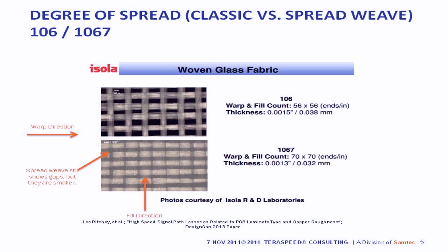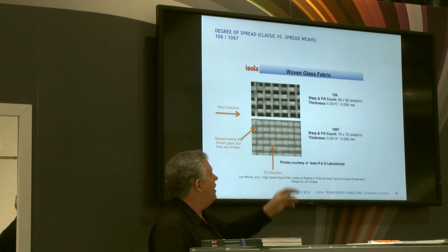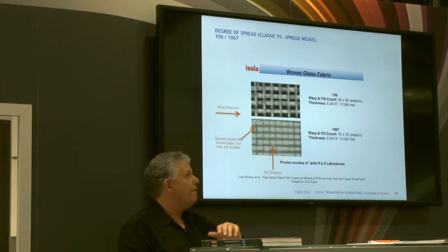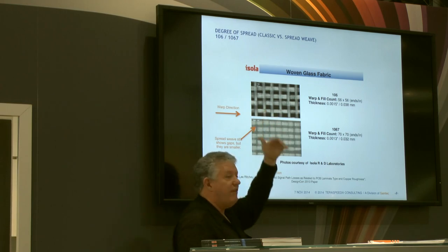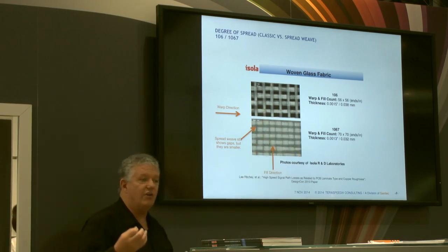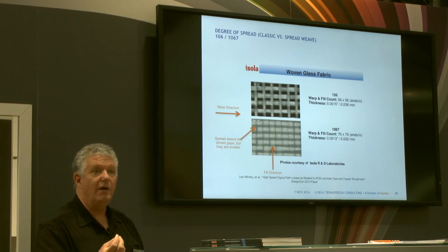It is 0.033 millimeters thick. It is very, very thin, but you see that there are large holes. In those holes is epoxy, which has a very low dielectric constant. Along the fibers, we have a high dielectric constant. So we can see that our material properties, our trace properties, our impedance control changes from region to region and direction across this printed circuit board.